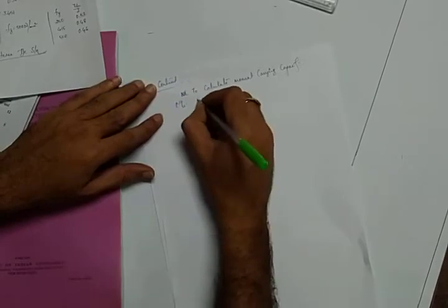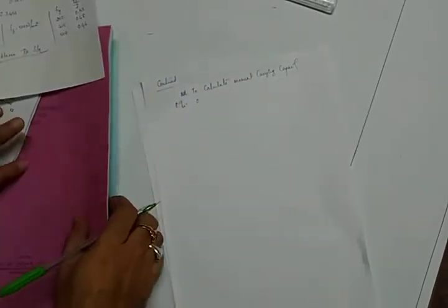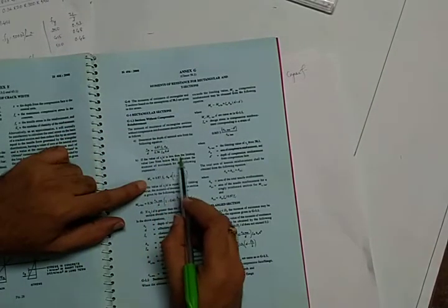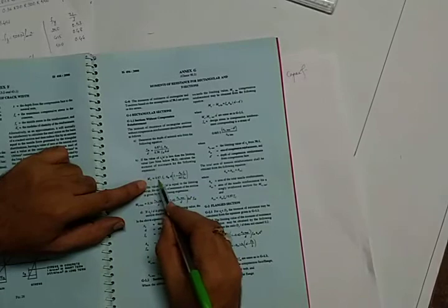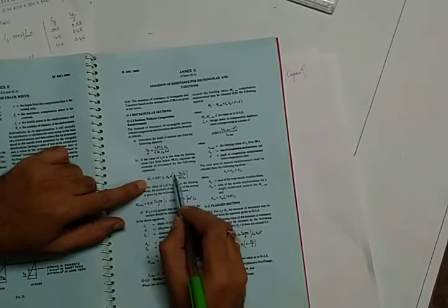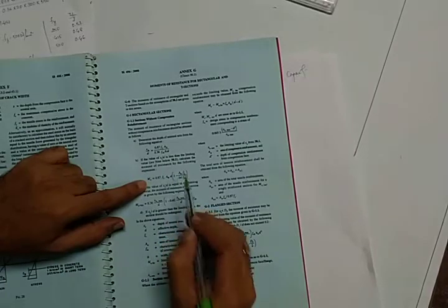Mu is equal to, we have a formula. Anyhow, I know that formula, but for your reference, I am referring to it from IS 456:2000. This formula is used to calculate the moment when Xu by d is less than the limiting value. Mu is equal to 0.87 fy Ast d, 1 minus Ast fy by b d fck. So this formula is used. Refer page number 96, Annexure G. This can be referred from this.